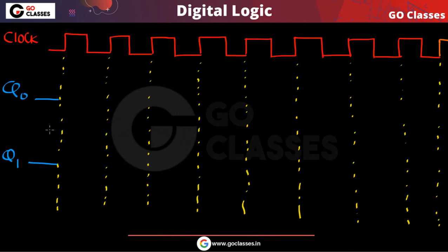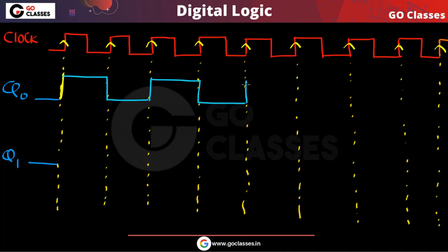Now let's apply this. Let's assume initially Q0, Q1 are both 0 0. Now what will happen with every rising edge? These are the rising edges of the clock, and the clock is only applied to the first flip-flop, Q0. So with every rising edge of the clock, Q0 will toggle. So like this, this is the output waveform of Q0. You can just write it like this.